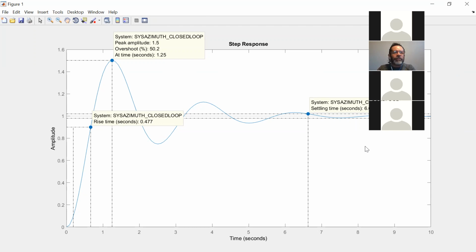So let's remember the line follower. In the first case, it's following the line, and the deviation we had in the previous case, imagine the line follower, was 4%. So you're going 4% past what you're moving. That might be acceptable, okay? Would it be acceptable that suddenly you go 50% off the target and then try to go back? What's going to happen with your car if it's doing that? In practice, what's going to happen? It wouldn't find the line again.